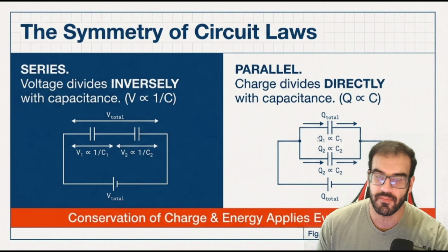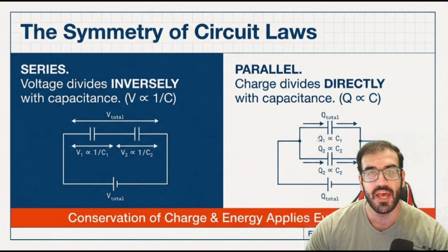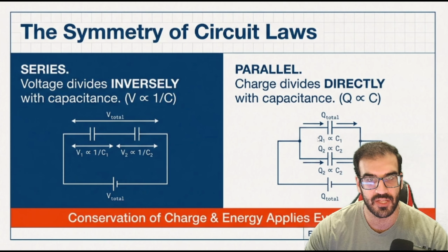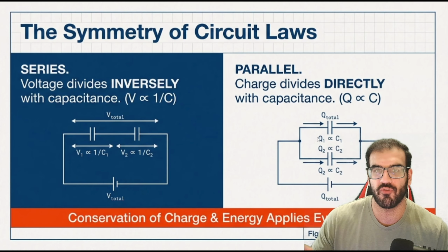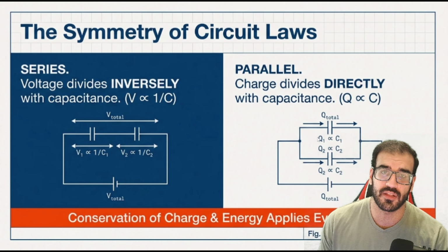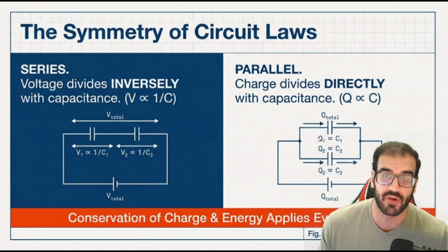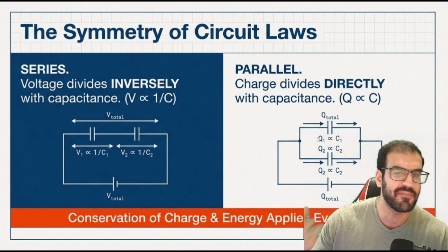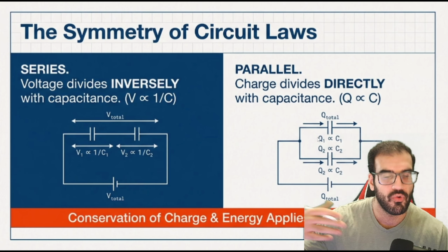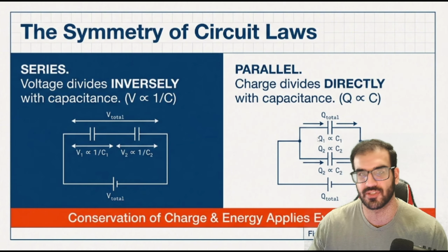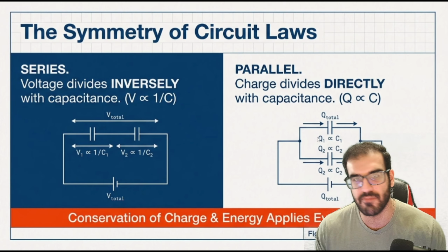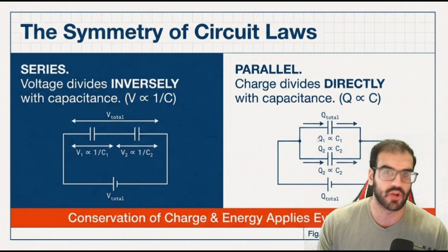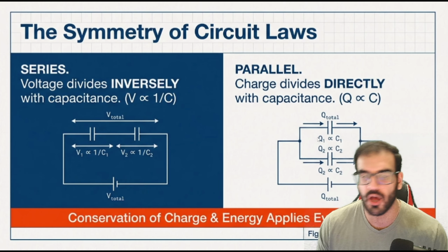And you guys have to remember, whenever we are talking about this condition, it means that your capacitors are already charged. It means that we passed through the transient one. Because maybe some of you would ask right now, you mentioned that the voltage of the capacitor is not going to be constant all the time, and it depends on the timing factor, which is obviously right and related to the previous chapter. But right now, we just assume that time has passed, after 5 tau, 10 tau, whatever, and everything is charged, we pass the transient timing and we just reach the stable condition. On that point, we can say that these numbers are right. The voltage of the capacitor is going to stay constant, the Q is going to stay constant,